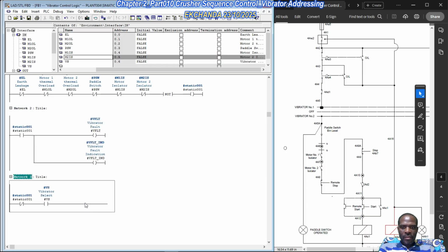Okay, so remote stop externally, I'm not so sure, I've forgotten the normal state in factory IO, but I should think it's normally closed externally, momentary action. So internally to be just normally open. So this will be as an input.